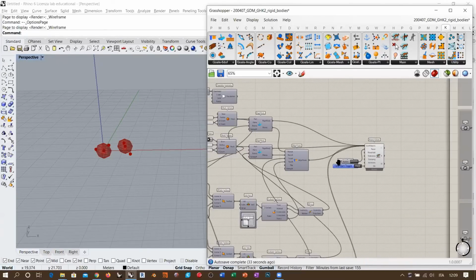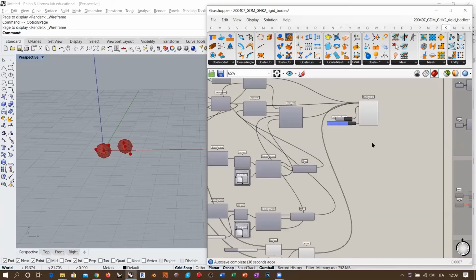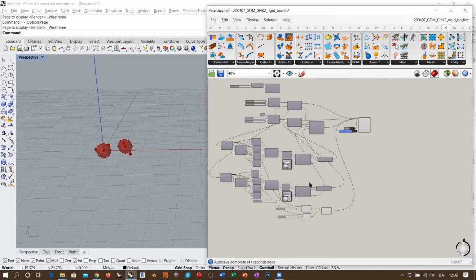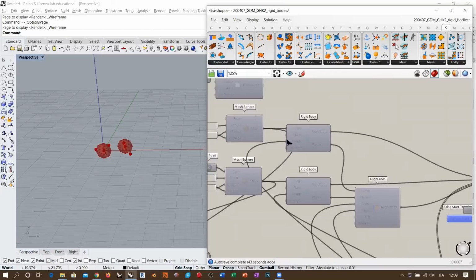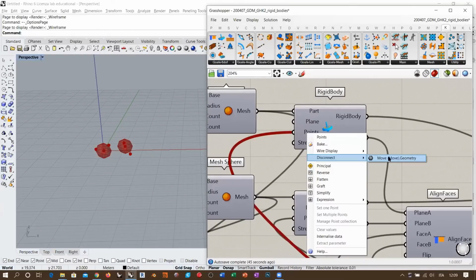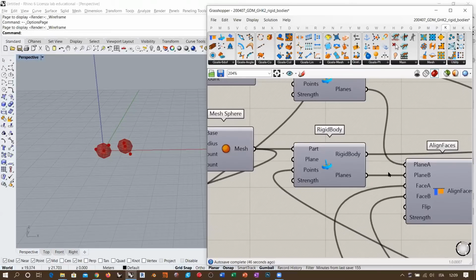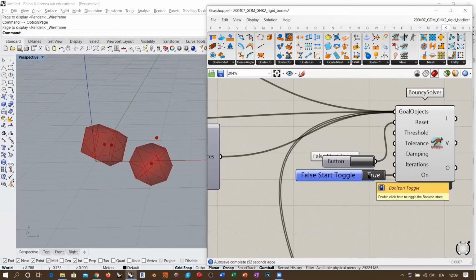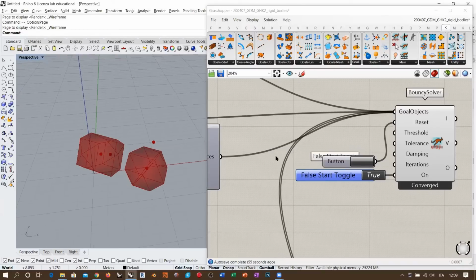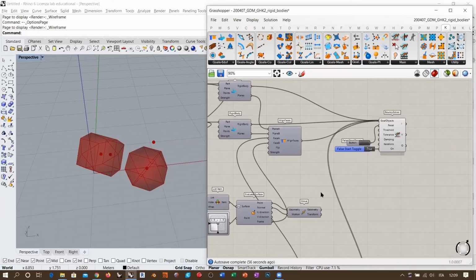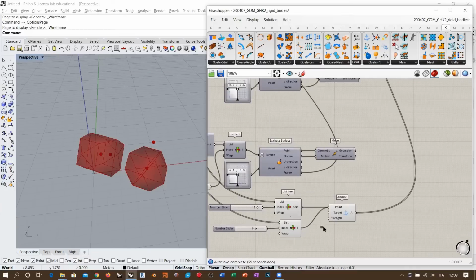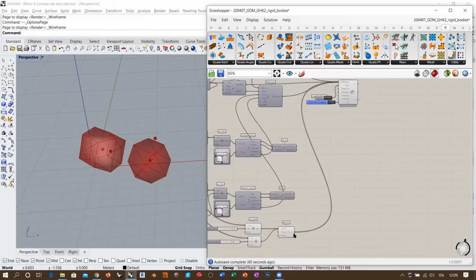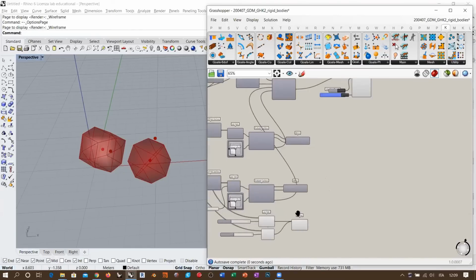So let's see how simple it is to work with the output in this case, compared to the problem that we get from the rigid points connected to our meshes. So what I'm going to do, I'm going to get rid of these points here. Okay, so I reset, I no longer see the points. And if I do this, you see that this rigid situation here is also stronger than the anchor point that we are defining for our meshes. So it's not, let's say, an effective way of working with the anchor point.